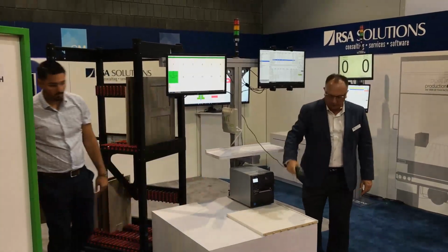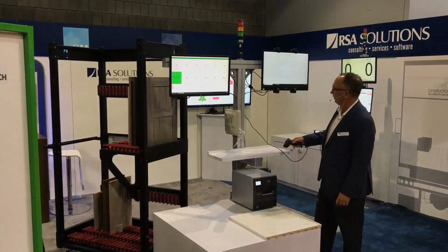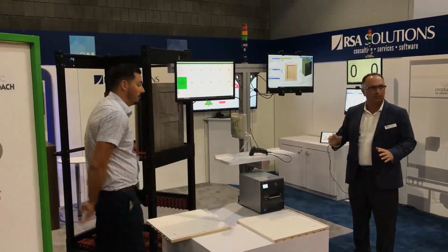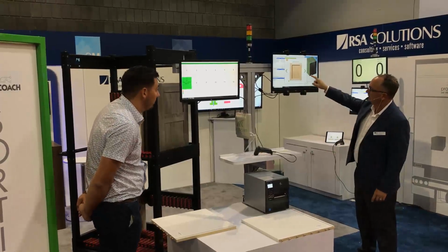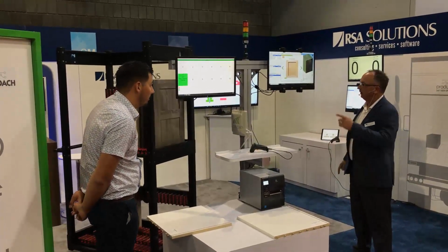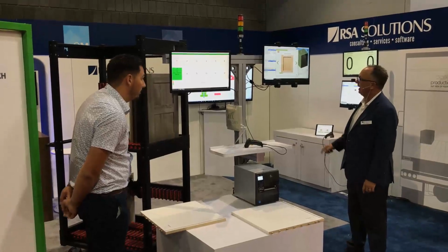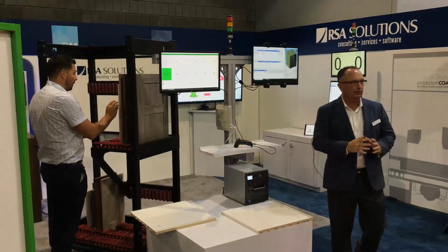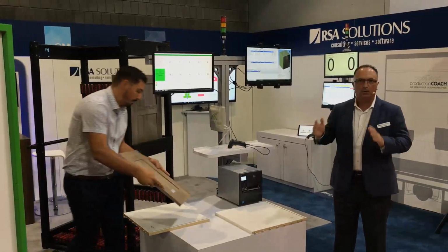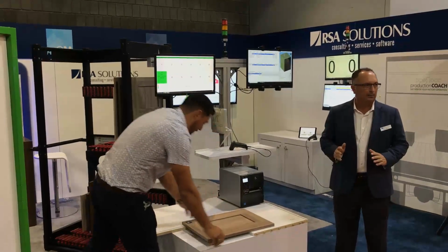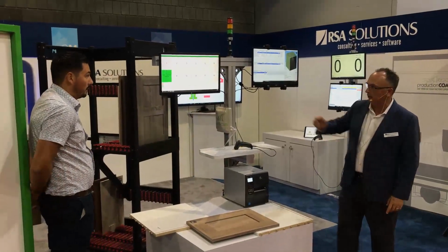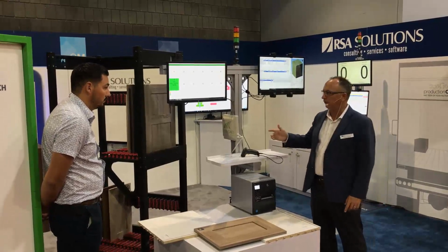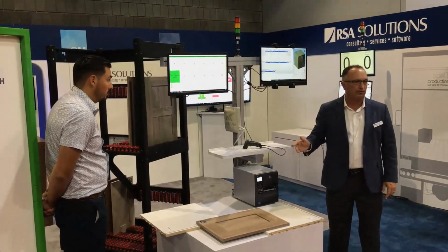With a simple barcode scan of any one of the parts, we're going to see that we are now beginning to help the builder. So here we will see that it is telling us, Jonathan, I need the door from bin A1. Let's stop for a moment and understand what's actually happening in this case. Not only did we identify that we had all of the case parts, but in order for that to turn green for the builder, it meant we had to have already sorted also the doors and drawer fronts for that cabinet.